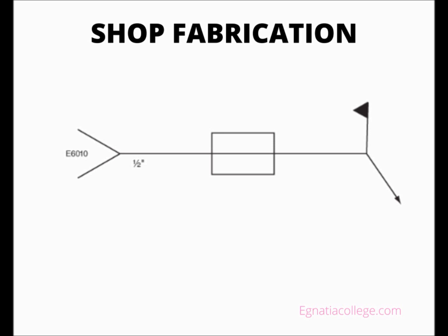However, it is important to recognize notes on the structural drawings that indicate a difference between field erection and shop fabrication. One example of such information is the field weld symbol. The field weld symbol is a small flag at the break in the arrow of the welding drawing. This symbol indicates the weld is to be done in the field, not in the fabrication shop.